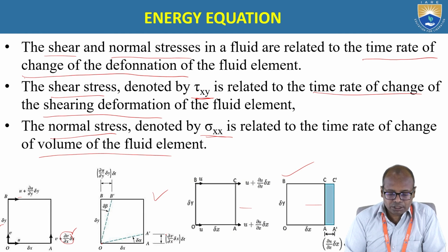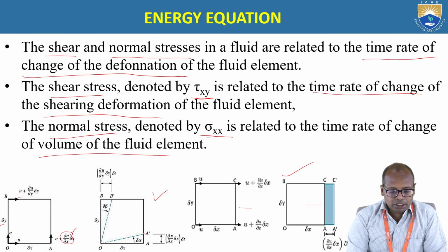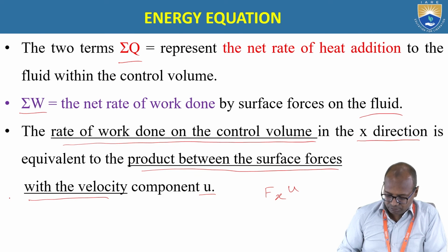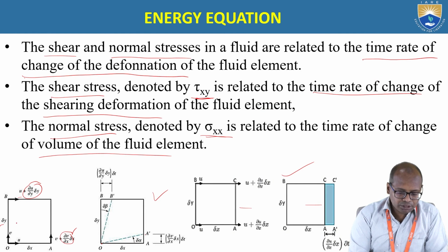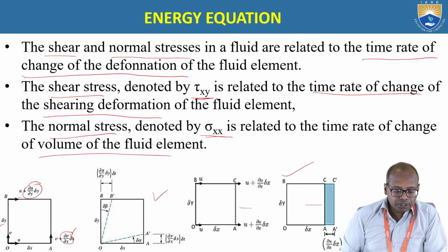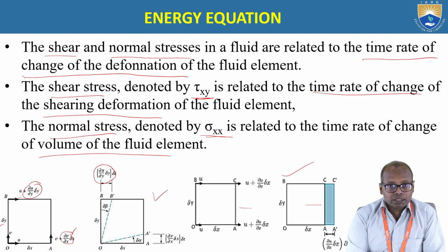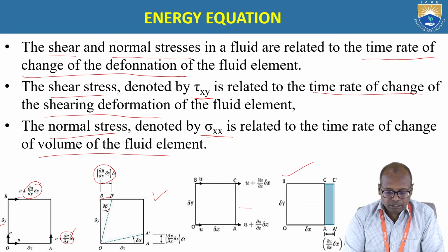What this relative velocity is doing is giving some angular deformation. Similarly, this is the relative velocity between this point and this point. Now this relative velocity is giving some angular deformation. So the relative velocity, if I multiply by time, I will get the angular deformation, and that is given by this beta here, and here it is given by alpha.